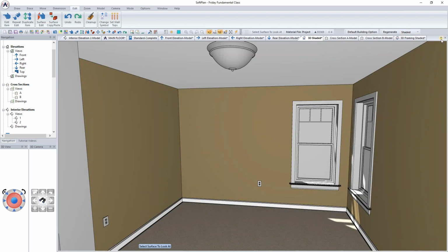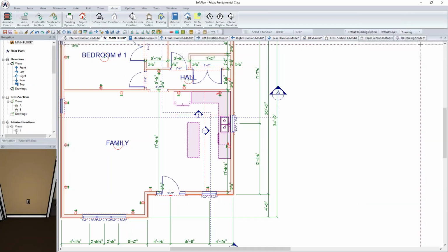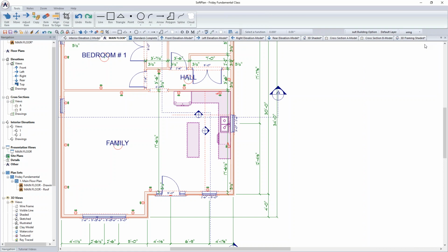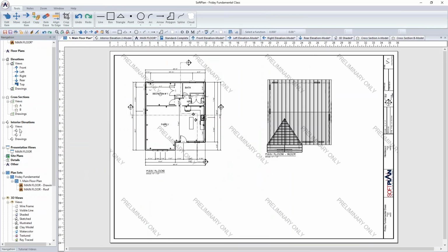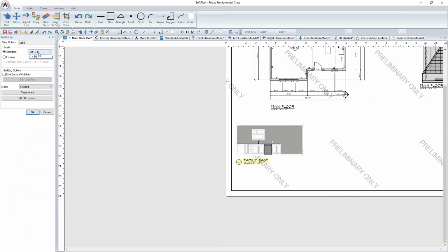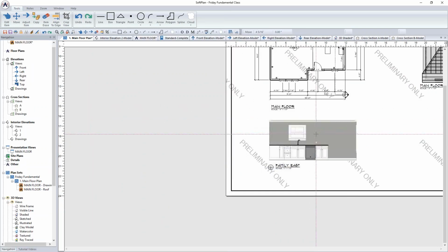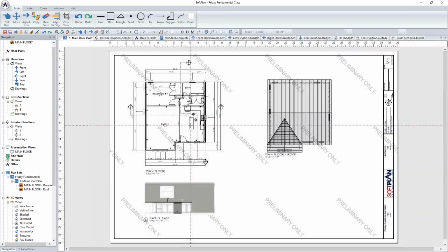And so as I come back to the plan set that we've been creating, I'll be able to come in and go to my list of interior views and drag and drop this onto the drawing itself. Now this is going to pull up something I'm introducing for elevations, model and annotated. In this case, if I just select model, it's going to give me a 3D representation of the drawing itself. I can then edit this, and I could change the shape or the scale on this to, let's say, 1/2 inch and move it into place. So that's my actual drawings.